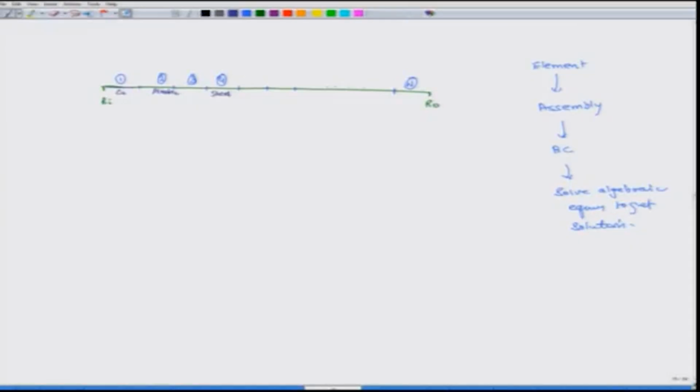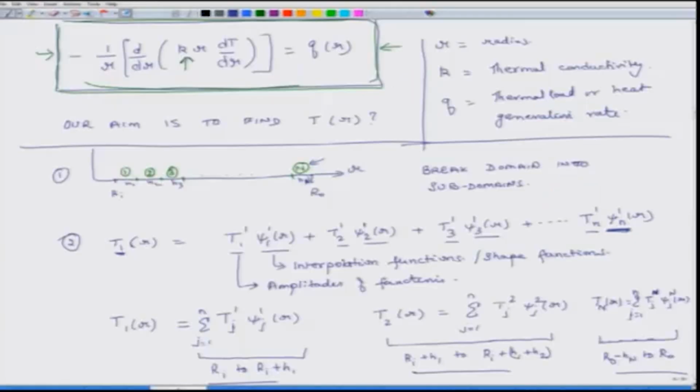If we had to use a traditional way of getting analytical exact forms, inherent in this method is the fact that it can handle variation of material properties very easily. If we use the traditional way to solve this problem, then we will have to integrate the differential equation, and while integrating it, we cannot assume that k is constant because k is varying.